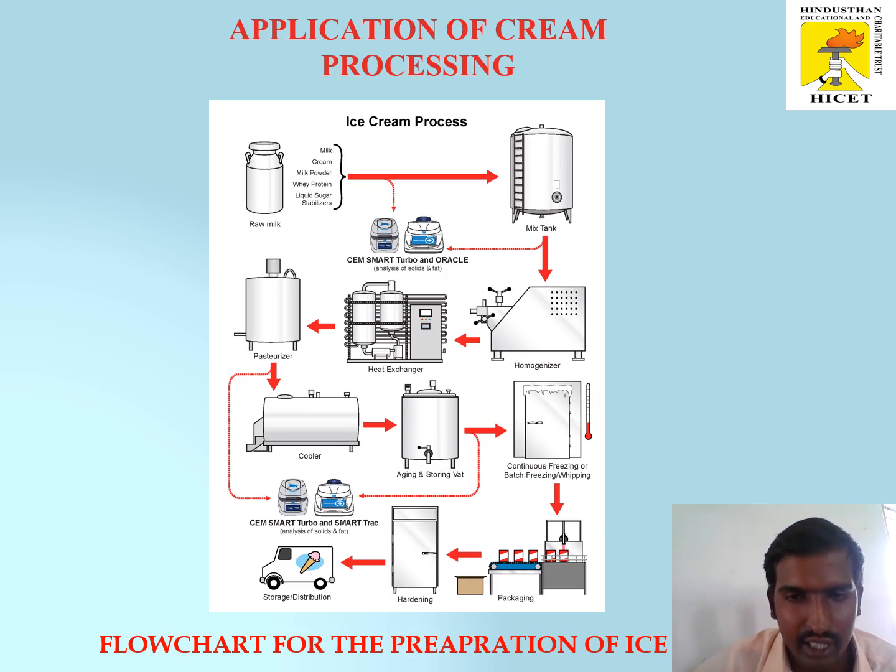After that it moves to a continuous freezer. At that time you check the solids-not-fat percentage and fat percentage in the milk, and then it moves to the continuous freezer where the freezing of the ice cream takes place, and after freezing it moves to the packaging section where it gets packaged, and after that it moves to the hardening section.